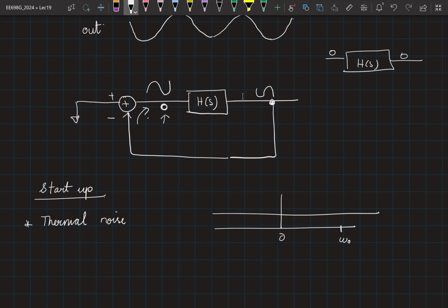If it is just turned off, we are trying to turn the switch on and turn the circuit on by giving some input. Correct. When we turn on the circuit, we have to make sure that it is oscillating and doesn't settle to 0. So one way is that we could rely on the thermal noise. Once it starts oscillating, there is very little chance that it will switch itself to the off state. It's not that it has started, right? If it doesn't start, that is the question.